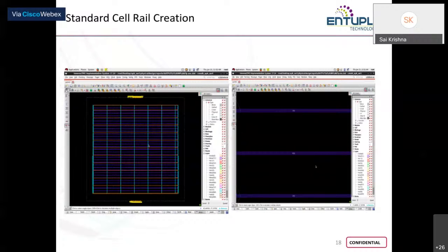Normally, if you already have a VDD and VSS pin declared, then you directly start with your power ring. But if that is not the case, you will create two virtual pins for VDD and VSS on the name of Global Net Connect, and then do this procedure of creating rings, strips, and then the rails. Okay, so this is your power plan.